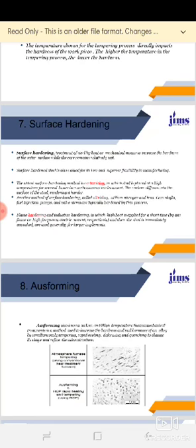It is the oldest method, and there are certain methods in surface hardening. Those are carburizing, in which steel is placed at high temperature for several hours in a carbonaceous environment. The carbon diffused into the surface of the steel renders it hardened.